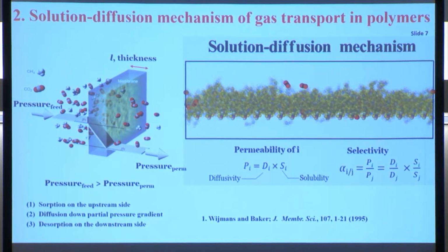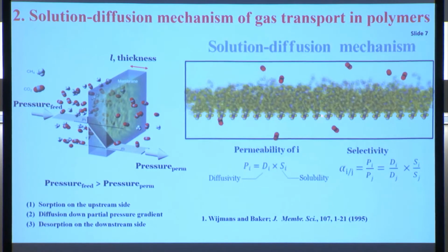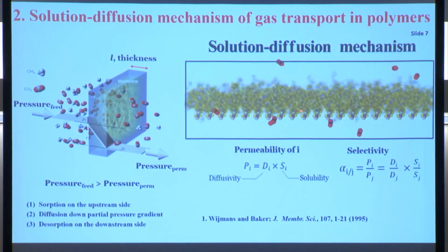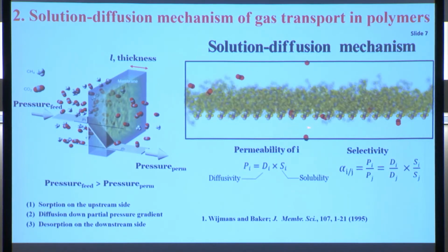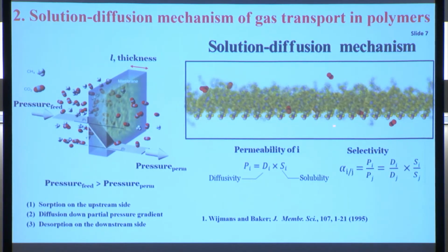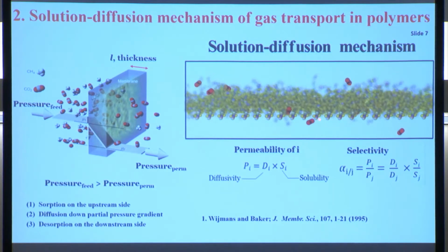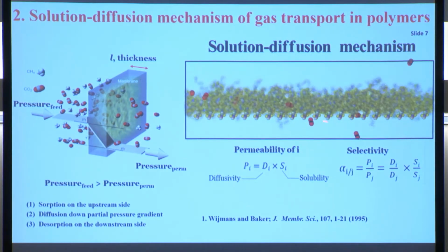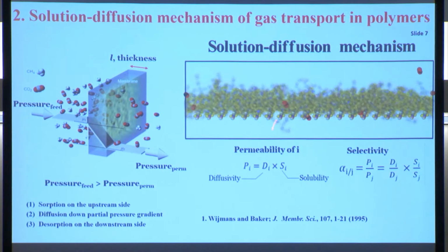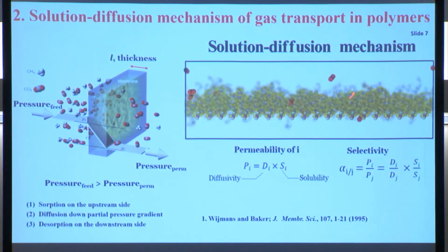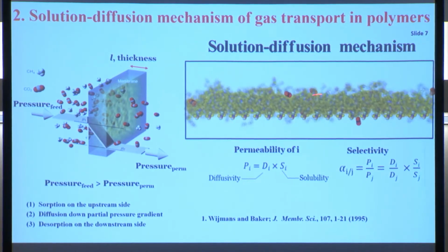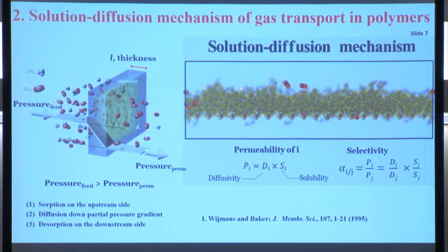the Hawaiian dance, the girl's skirt. The pore size is smaller than the CO2, but when the CO2 molecules penetrate through the membrane, the pores can change to become larger. So the CO2 molecule is dissolved in the membrane and then penetrates through the membrane. So it is called the solution diffusion mechanism.